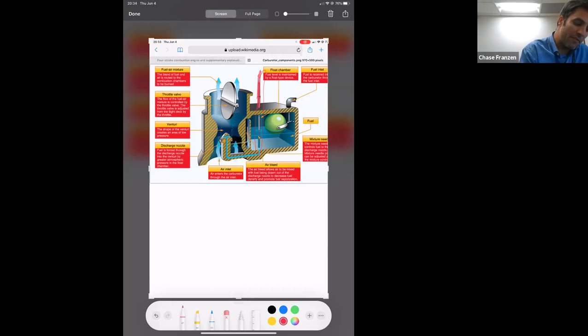So you've got fuel that's sitting in this fuel reservoir here. The fuel comes into the fuel reservoir, and as the fuel goes down in level, this float goes down and it opens up a valve right here that allows fuel in. In the Cessna 172, you've got a gravity-fed fuel system. As the ball goes down, the valve opens and you dump fuel into this reservoir.